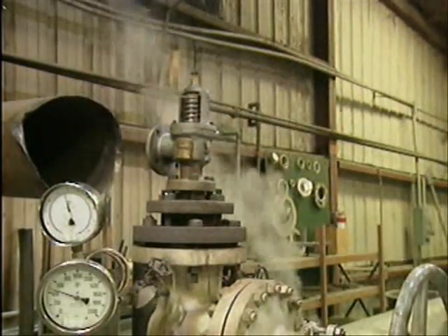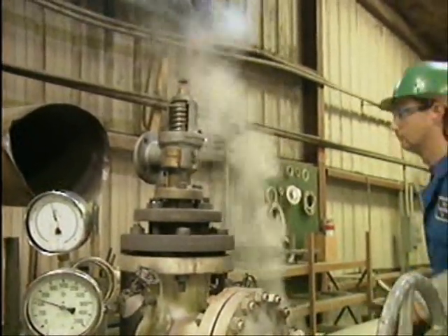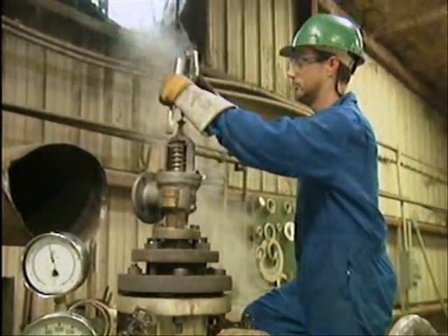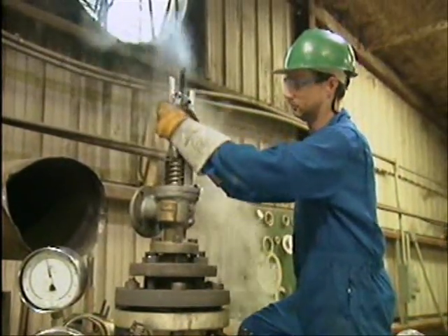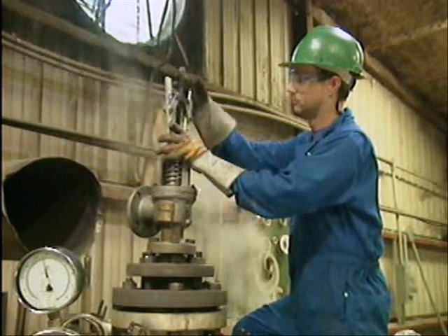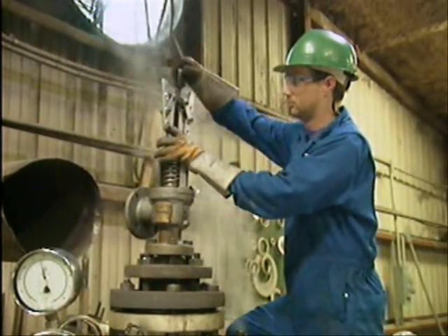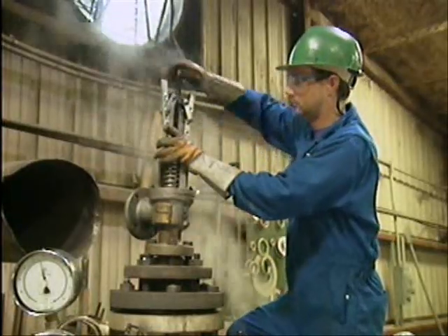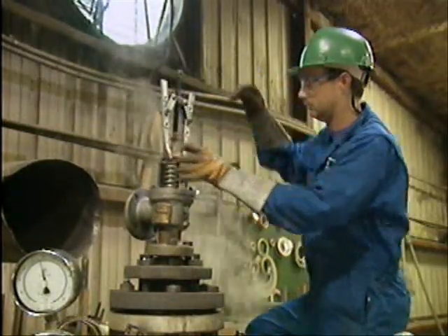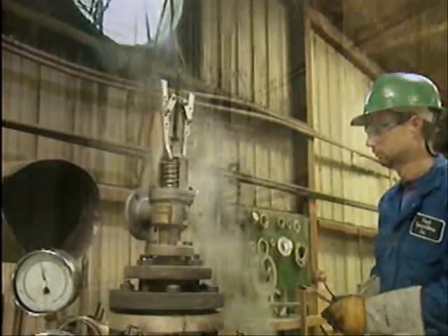Hydro tests are often performed at system operating pressure and below safety valve set pressure. But in some cases, during hydro testing, system pressure is raised above the normal popping pressure of the safety valves in the system. Then, gags must be installed on the valves before the hydro test is begun.